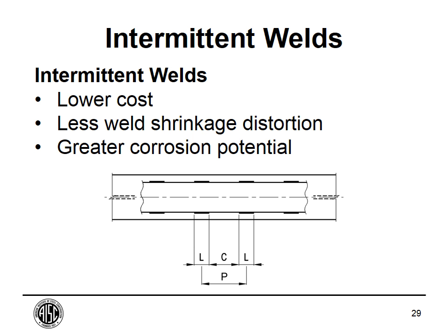One of the things I like about stitch welding is that you get a lot less shrinkage distortion. If you were in on part 1 of this webinar, you'll realize from the plot I had on the column curve that the out of straightness of your member that can be caused by the weld shrinkage distortion causes a huge reduction in strength to your columns.